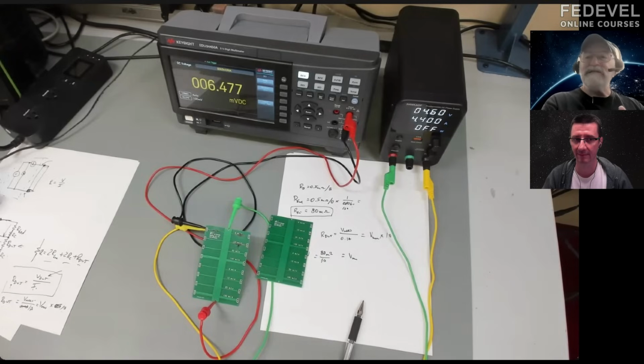And we know what the resistance is. So when people say, "Oh, narrow lines, they have a lot of resistance," well, a lot is a relative term. Put in the numbers. We just saw a 6 mil wide line, 80 milliohms per inch. Is that a lot or a little? Well, it depends on the application. If I'm putting an amp through it, we saw 80 milliohms per inch, which was 80 millivolts. Is that a lot or a little?